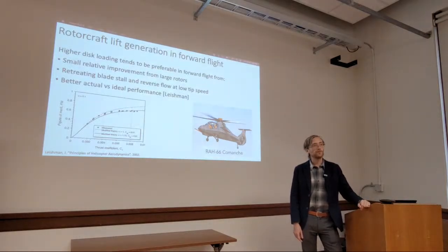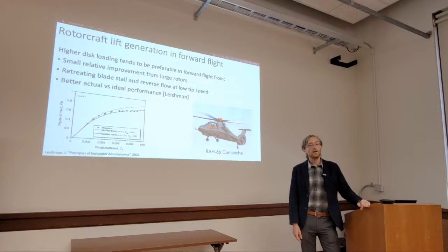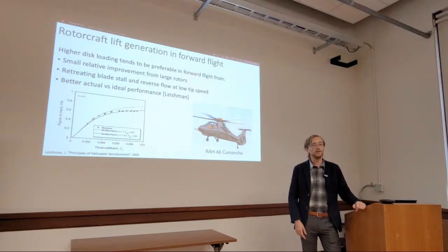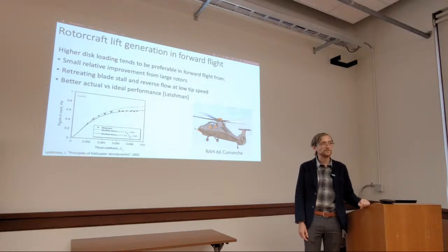But this type of hyperbolic pitching or twisting of the blade is actually seldom used in practice because it's hard to manufacture, and also because it reduces the overall efficiency in horizontal flight. So it shows another design choice that results in a trade-off between efficiency in hover and in forward flight. Thank you for your question.